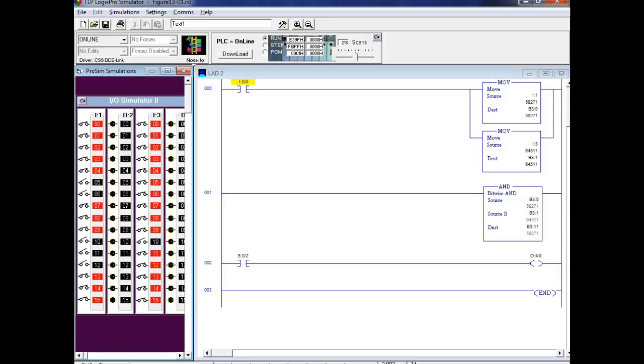But you could come up here, you could clear it, you could set it, you could jump somewhere, you could jump over here and do a certain program if that bit comes up to be set, right, or cleared. So it's up to you to do what? It's just like a counter. The counter, once it's done, it generates a done bit, except that done, instead of me addressing it as a bit, it's got a name, right? If I don't use that done bit somewhere, right?